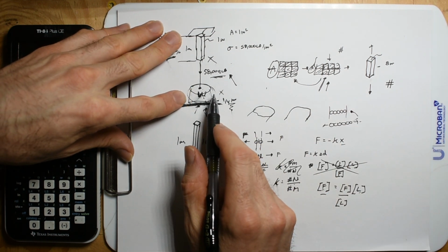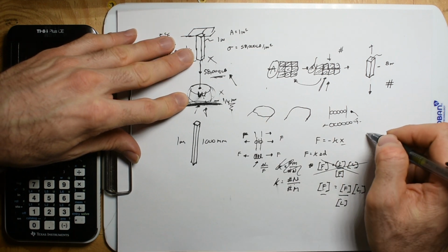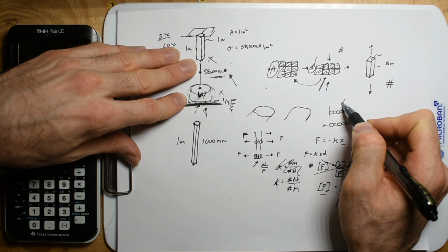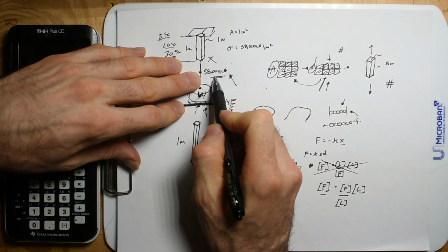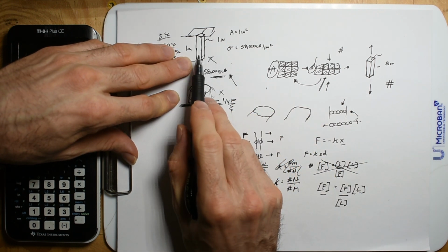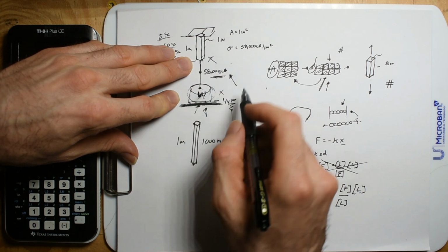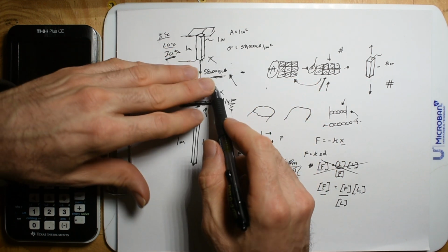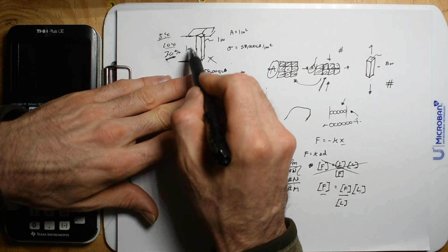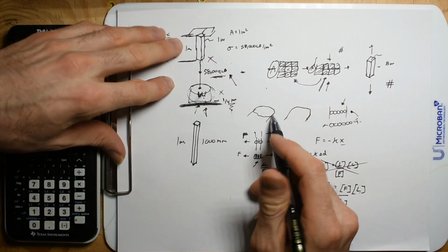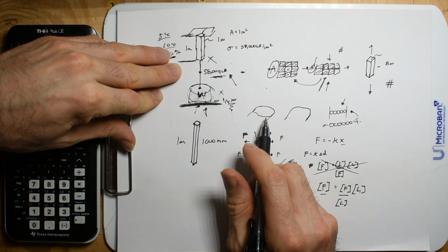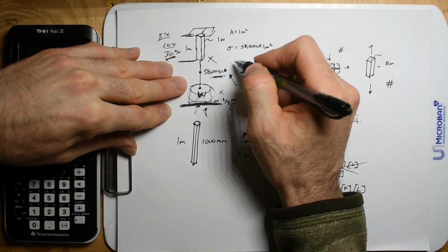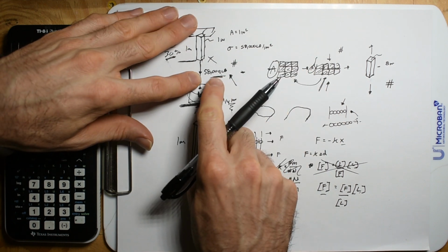It's not even just that if you put 10 pounds on this steel, it's not going to go back. You can put up to literally 58,000 pounds on this 1-inch steel bar. If that's right at that limit, you take that weight away, and this bar goes back to exactly 1 meter. Every molecule is in the same location. And so that gives us the high end, because you don't actually get too much more strength.